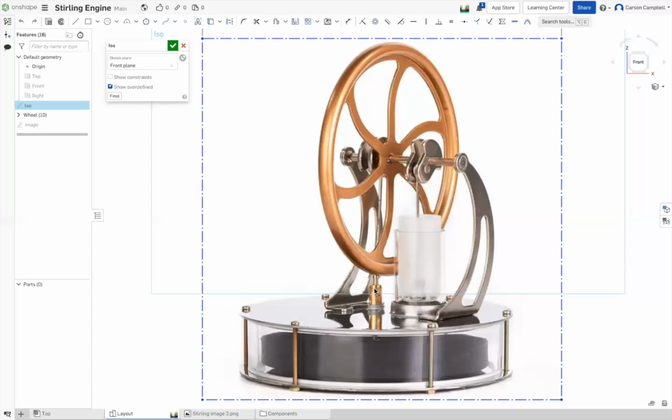There will be instances where this change has nothing to do with the rest of the model. And I would say, okay, then do that in its own part studio. There's another change. All these parts are going to be modified. Okay, now I have two part studios, because I have two things that are totally independent of one another, but I have two things that have a lot of dependencies. Therefore, that's describing two part studios. And then I have an assembly that puts it all together. Or I can have a bunch of parts because I really don't care about the interdependencies. Something tells me that more often than not, you're going to want to have multiple parts inside of part studios.